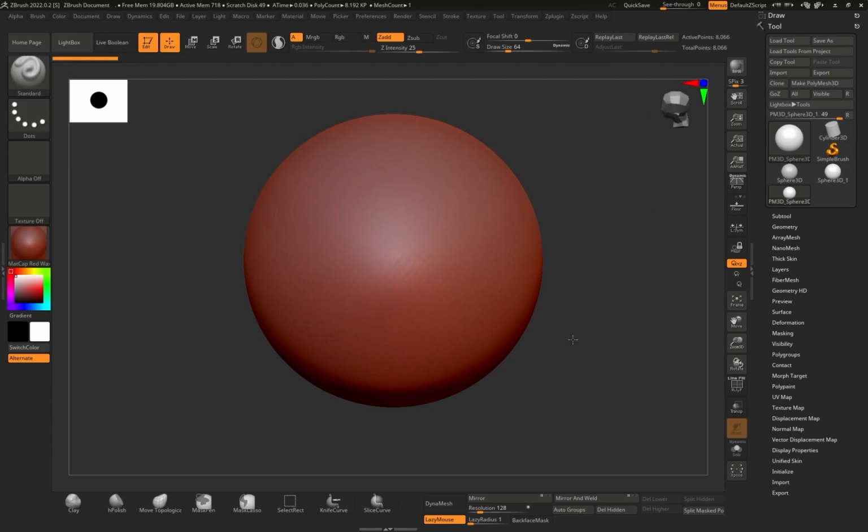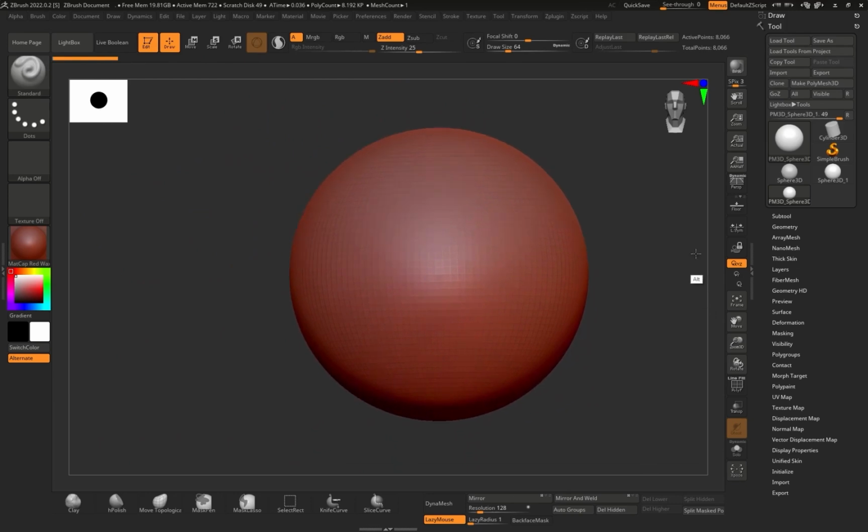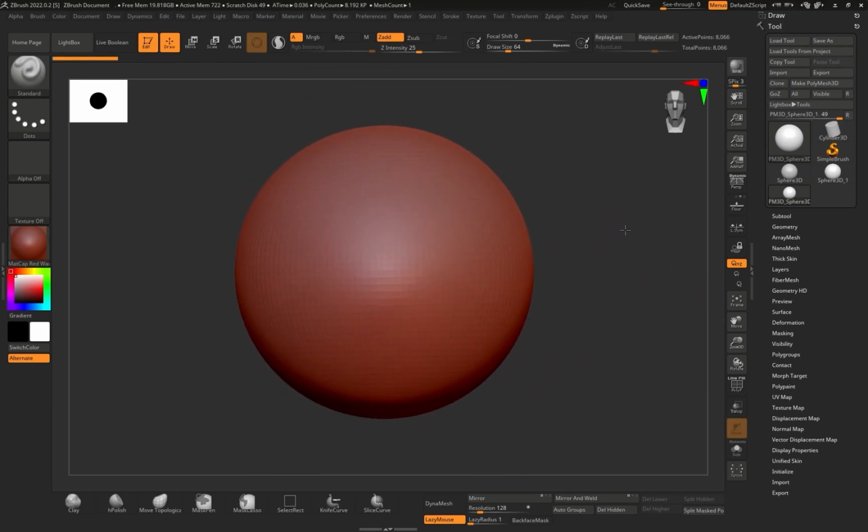Okay, next up is the movement in two spaces. So basically panning, as we say it. So we have movement in 2 spaces, left, right, up and down. We can do that by holding Alt and just moving with the mouse and pen, as you can see, and we move in 2 directions, so left, right, or up and down. This movement is called panning. So you can switch between those two. All the movements are located on the right side here.